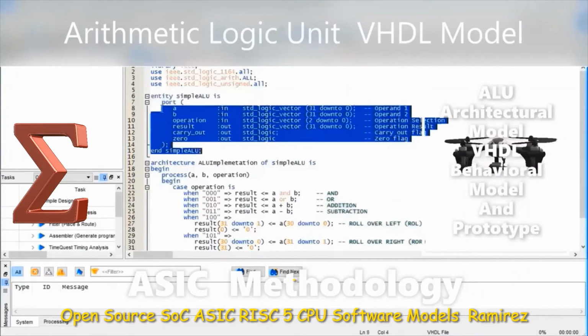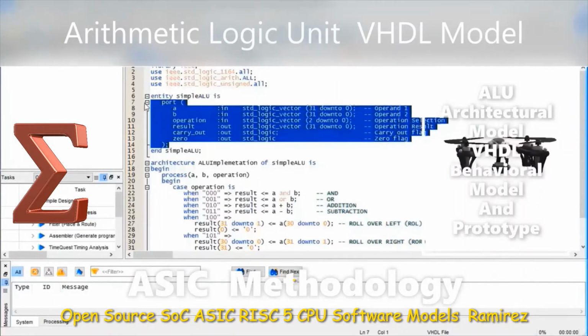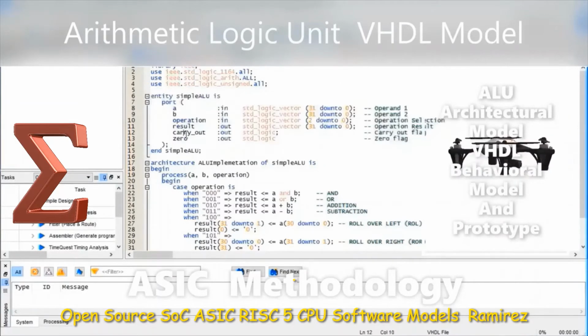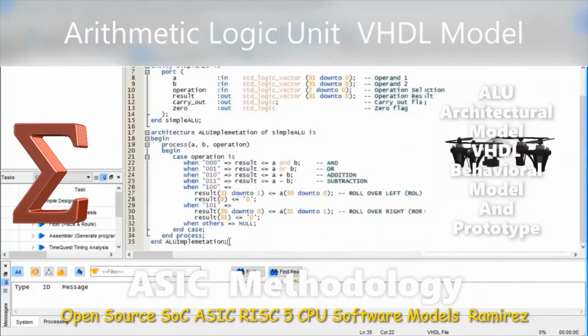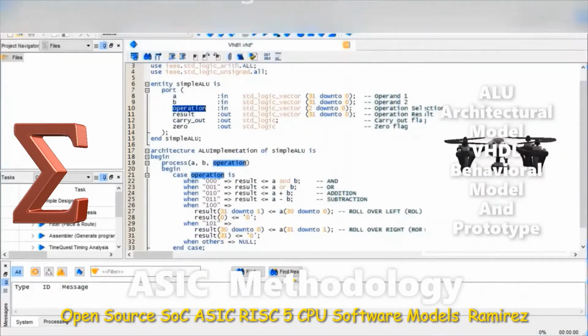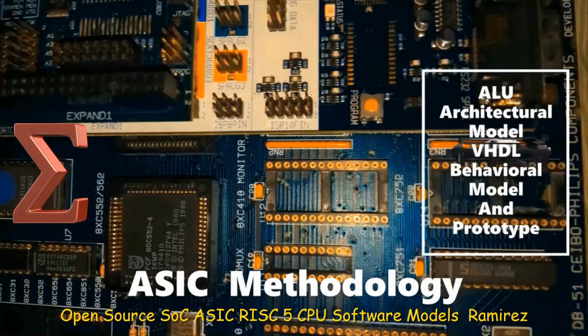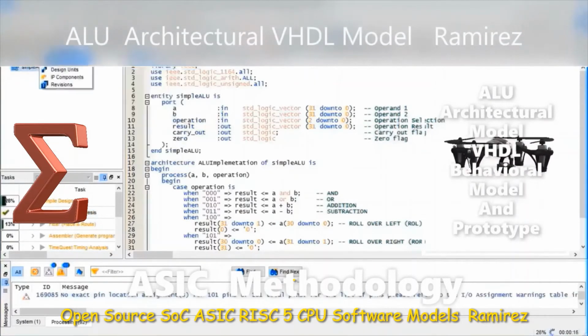Also, I have used the when statement. In the case statement, it executes many sequences of statements based on the value of a single expression. Also, the case statement evaluates the expression and compares the value of each of the choices, while the when clause statement corresponds to the matching choice, which will make the statement to be executed.